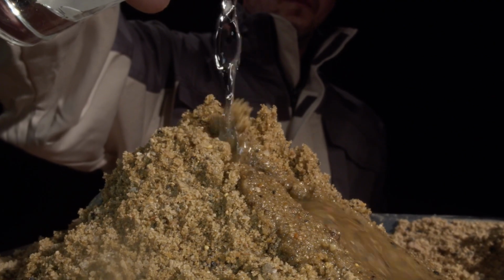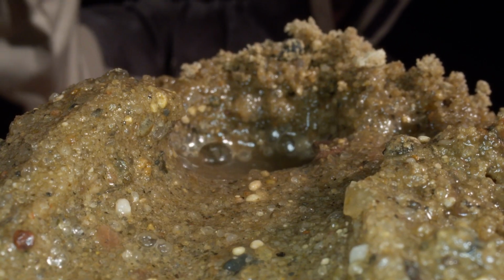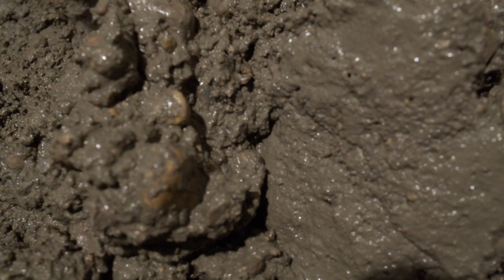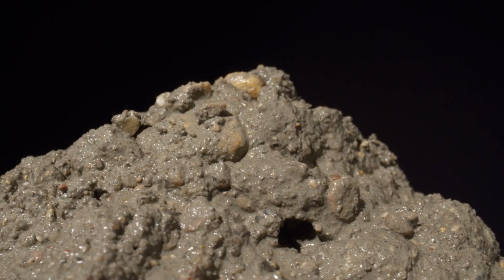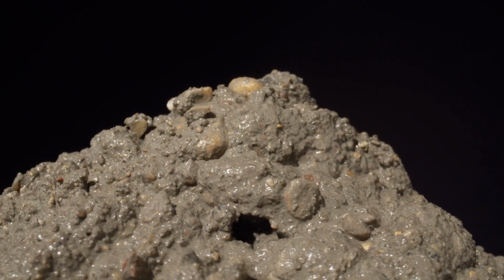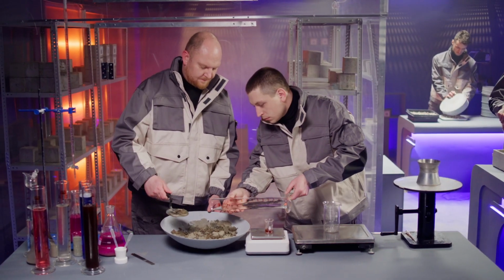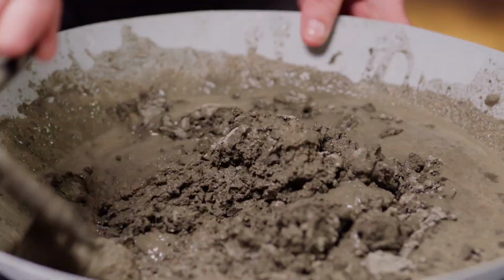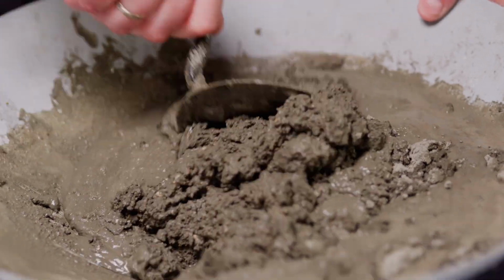The right amount of water in the mixture is the key to the quality of concrete, its strength. Excess water will inevitably reduce the strength of the concrete produced, as it will increase the water-cement ratio. And this is one of the most important characteristics when calculating the formulation of the concrete mixture. In other words, in order to achieve high-quality products, the water consumption must be within the narrow limits defined when designing a particular mixture formulation.